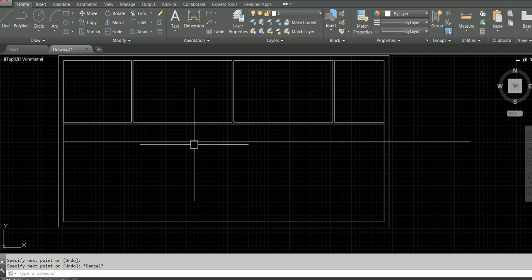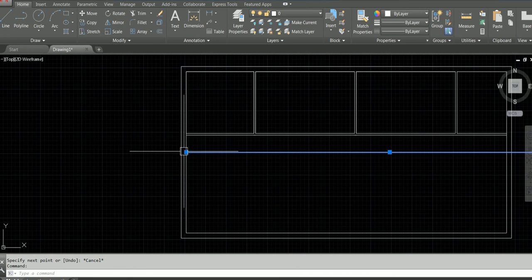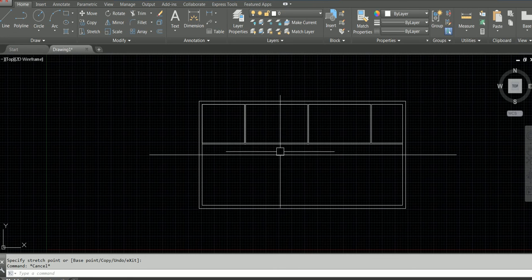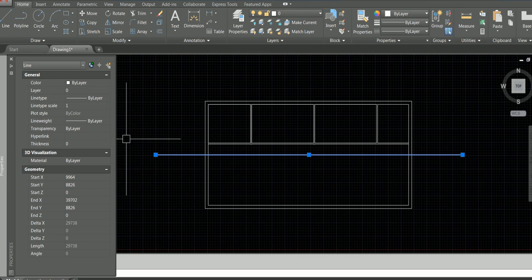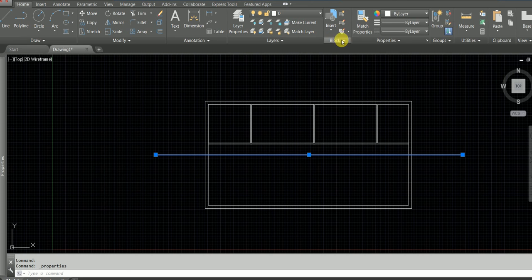Now a lot of questions have come from this discussion. John, how do you draw a center line, a hidden line? It's the center line mark. Different methods are there. One of the easiest is to select the line, press Ctrl 1 or right click properties. Then it's the line type. Click here, load, not loaded, isn't it? So what we do is, where is it?